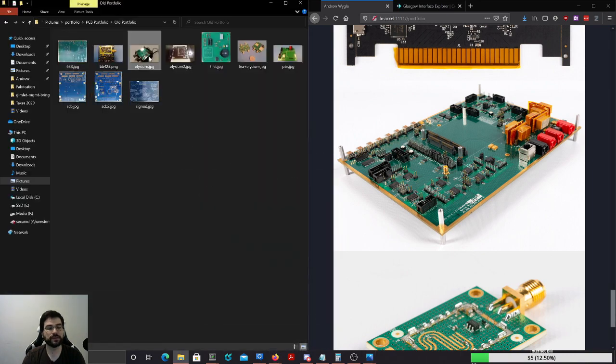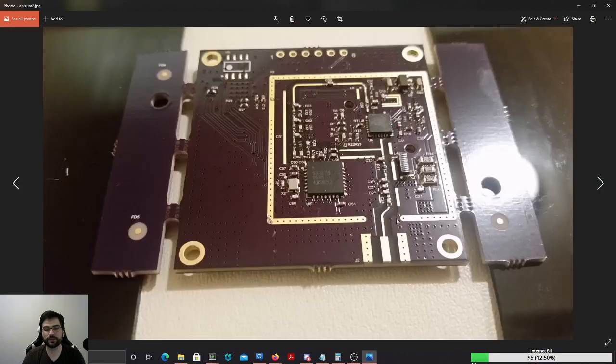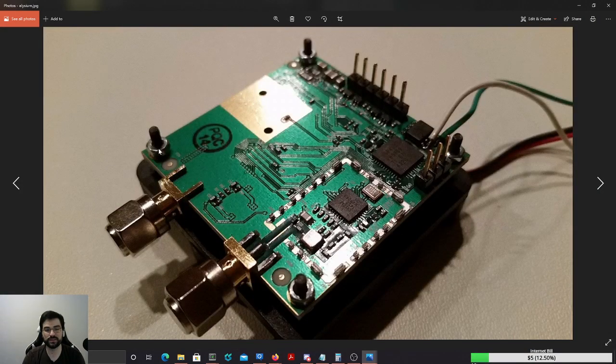And then let's see here. So here's the Elysium hooked up to its air conditioner. This is just a fan because you need to heat sink that big power amplifier. Okay, so I said it's 50% efficient and it goes up to 5 watts. That means that if you run it flat out, it dissipates 5 watts of heat in not a lot of space, like 8 millimeters square, something like that. So you need something that will cool it off and sink the heat away. And so I have this big fan strapped to the bottom of it.